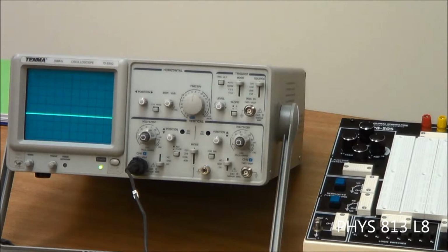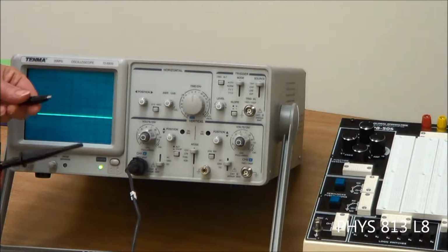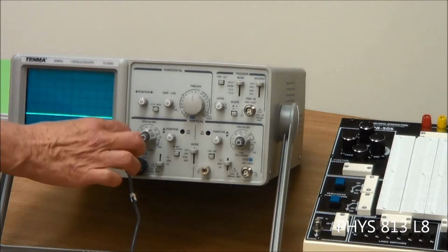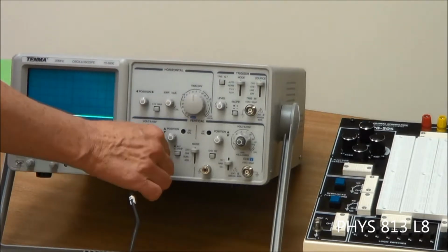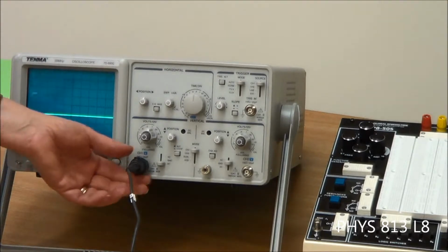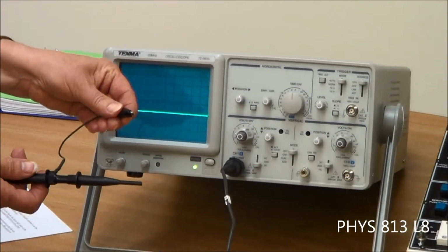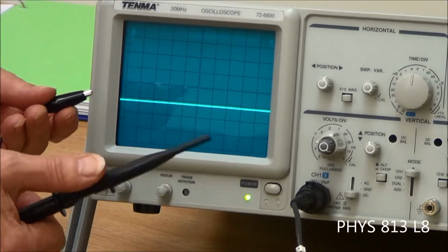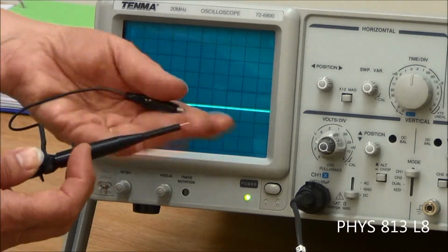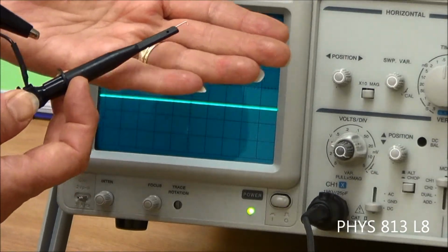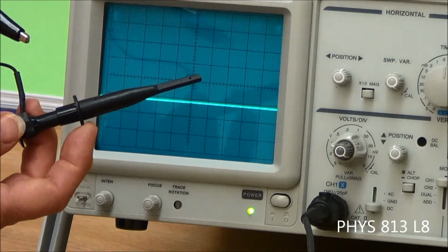On this, about in the middle of page 64, we're going to connect, and I said this before, but I'll say it again. We have the probe, and when you put it on here, you have to hold on to the part that's rigid and then push and turn it till it clicks. If anything's loose, then it's not connected correctly. We have a ground, which we're going to call the probe ground. We have the probe hook, and you pull this back and there's a little hook. It hooks onto something and then you let go and it stays hooked onto it.